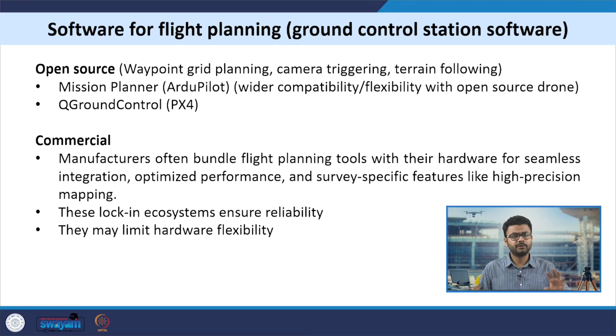There are majorly two different streams to go about it. There is the open source way, which helps us in waypoint grid planning, in specifying the spots for camera triggering, also known as exposure stations, and also gives us the option of executing features like terrain following. The popular open source software is Mission Planner, provided by ArduPilot. It has very wide compatibility and good flexibility with open source drones. So if you're creating your own drone, then Mission Planner is one good software that you can use to plan a flight with a drone developed by you.